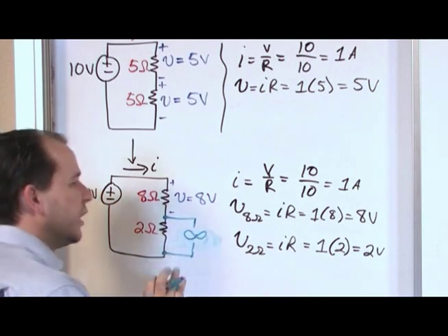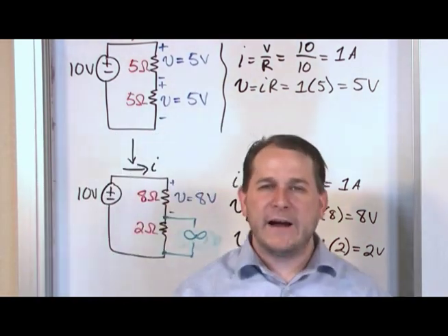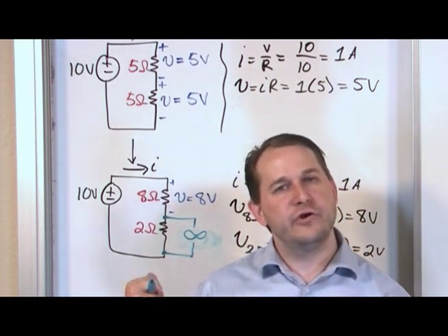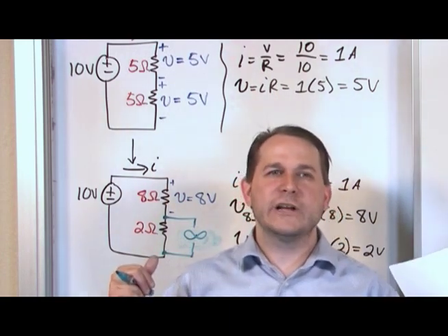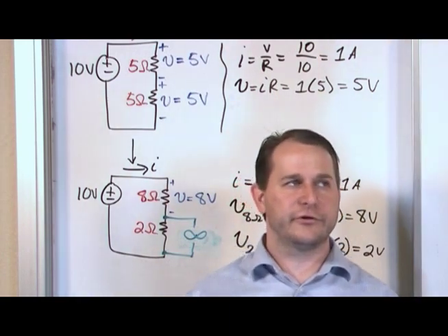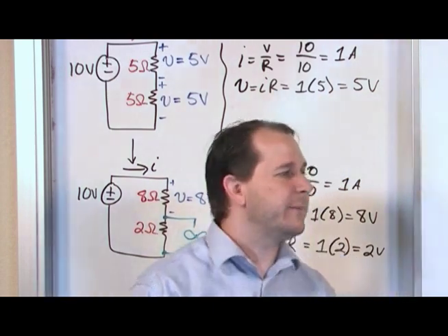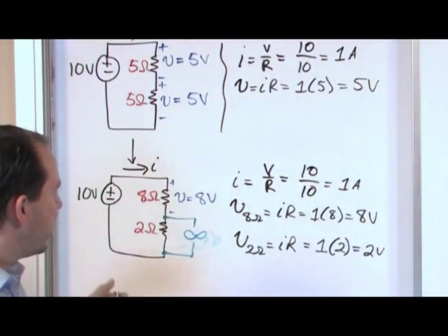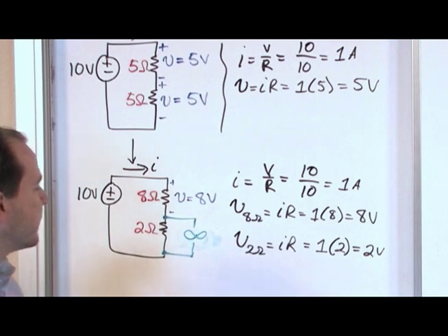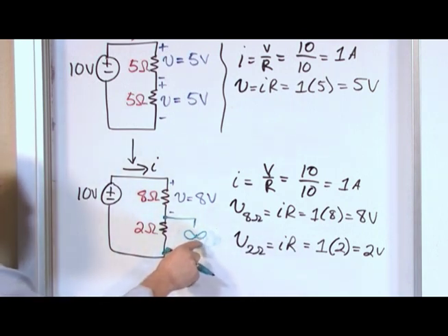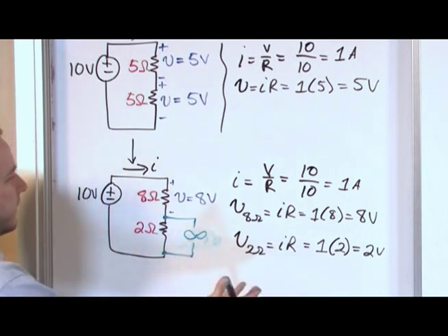So if I connect a load that has a very, very high resistance to my voltage divider, then I haven't really altered anything. I haven't really altered my circuit. So I'm still having a pure 2 volts delivered. Everything is cool, right?